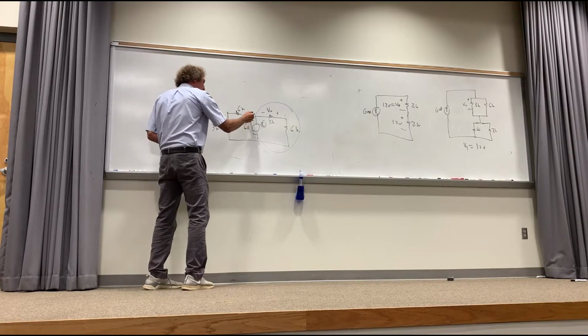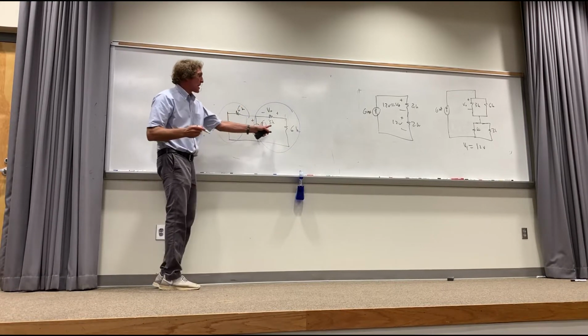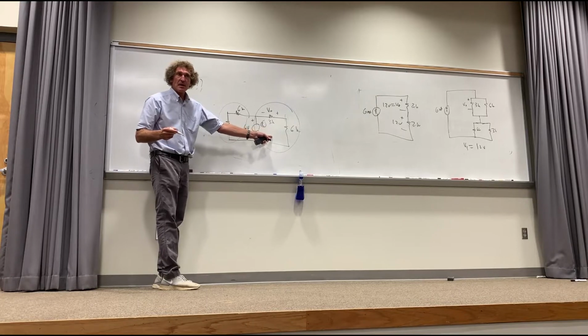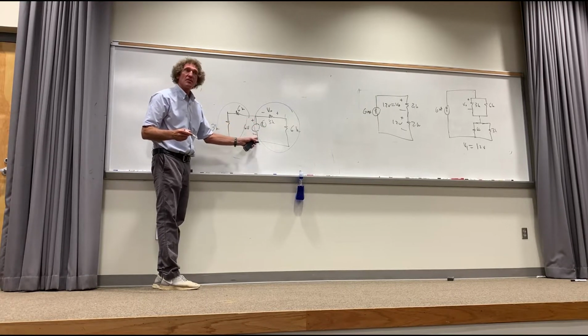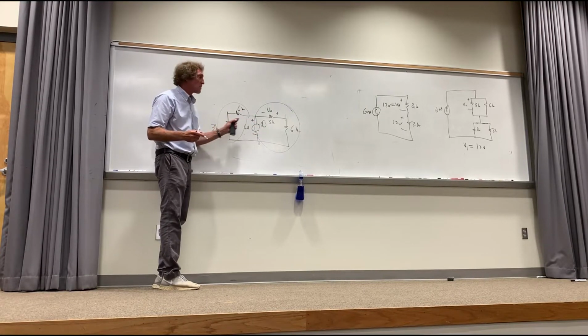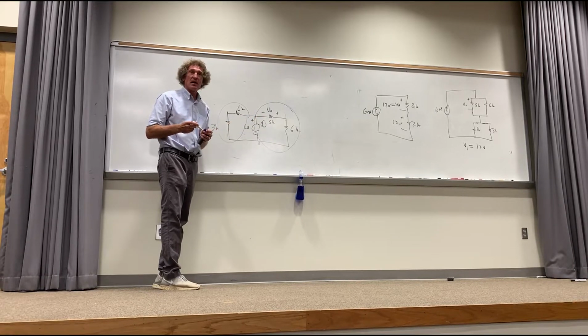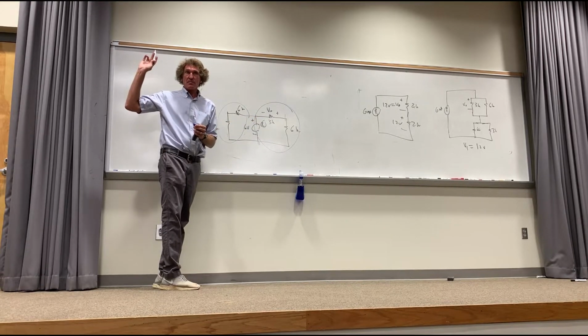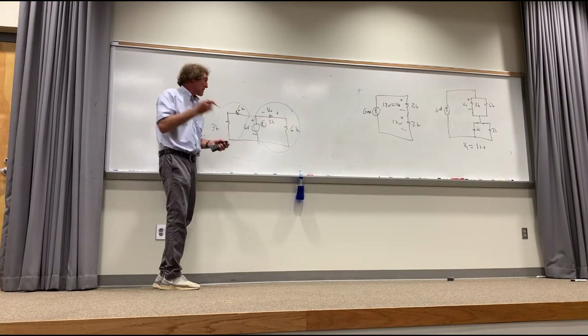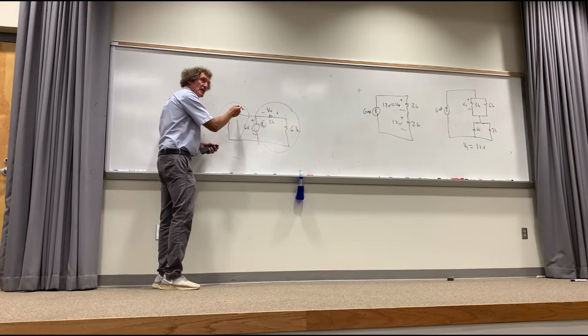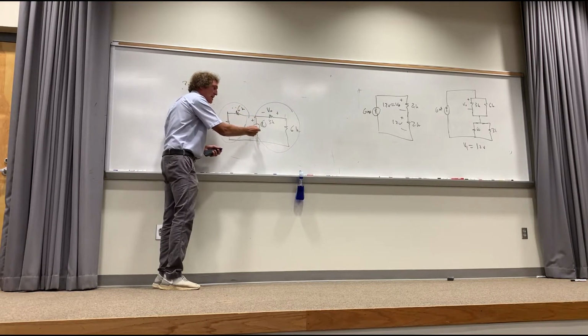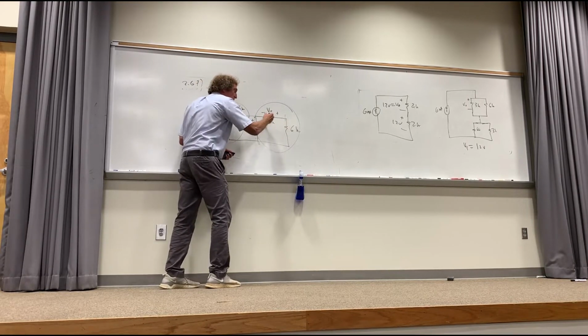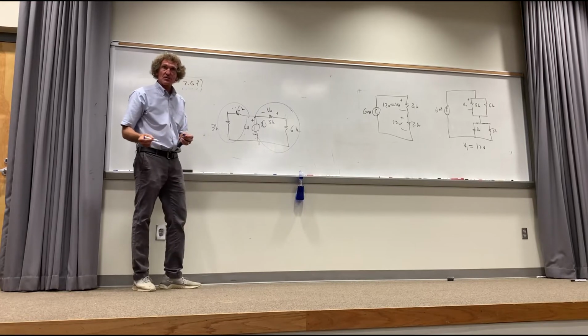These 2 resistors have the same voltage across them, but they have no impact at all on what's over here. Do you all see that? Because the voltage is defined over here. You can put anything you want over here. It's not going to affect that value of V naught. How many see that? You good with it? I can make that 50 ohms, 5,000 k ohms, it doesn't matter. This voltage is the only thing I care about because these 2 are in series. Are they not, class? Do you all see that?